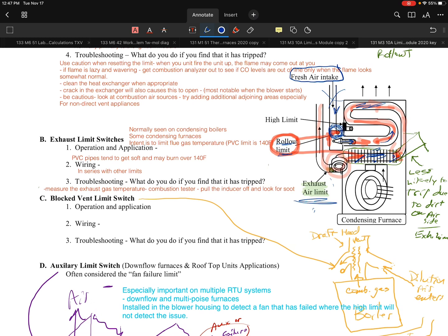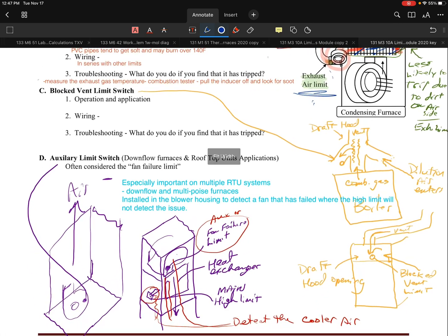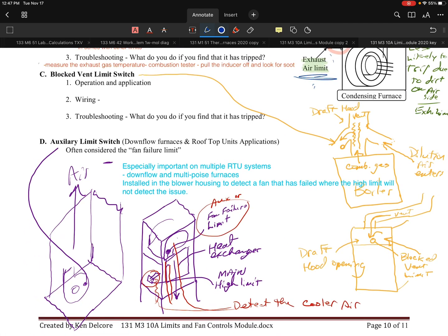And you may end up getting, let's say, 300 degree temperature of combustion products traveling through that secondary exchanger and not really extracting a lot of heat. So that's the logic of the reason why they're doing it. You're looking for whether it's an overfiring situation, which is unlikely, but that's one of the things that you're looking for related to that. So that's the one area to address that. All right.